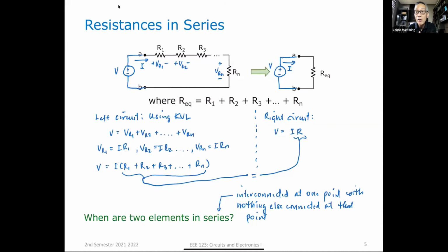And therefore, how can I define VR2? So I will not be able to combine R2 with the other resistances if my unknown is VR2. Otherwise, I am not preserving the unknown quantity that I want to determine. So that's very important in circuit simplification.